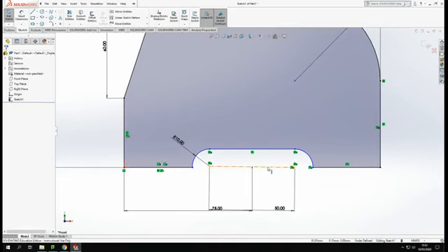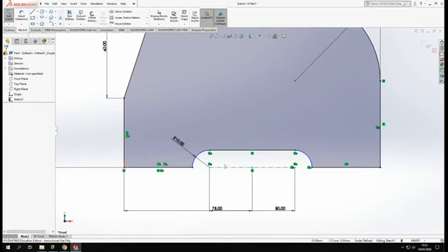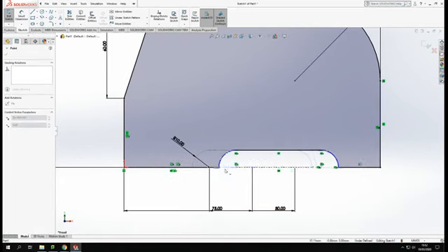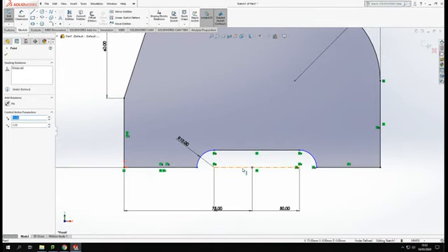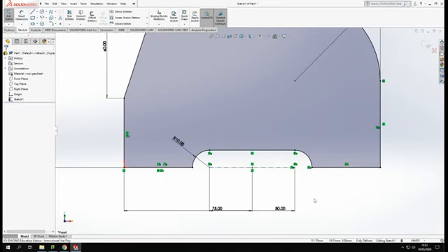Let's have a look what it is. That line there, I just want to make that horizontal. And we should be starting to get somewhere now. Okay, so it's just pulling along there. So that point and that line, I'm just going to make them midpoint coincidence. So you can see there how if I grab it and drag it around, it shows me what's wrong.